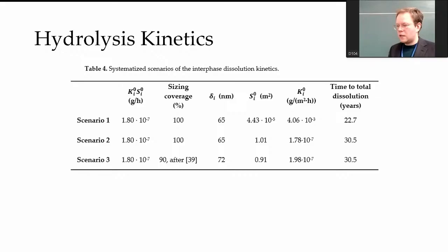It's a good question. Yeah, so the typical problem, I would say, is the cycling. So it's maybe not the temperature itself, but the change of the temperature, especially if it changes quickly from very low to higher and then again. So these cycles, the thermal shocks. I would say so, yeah. But also liquid hydrogen, the containers, the pressure vessels, this is also a topic where this comes in. Yeah, clearly. Thanks a lot.